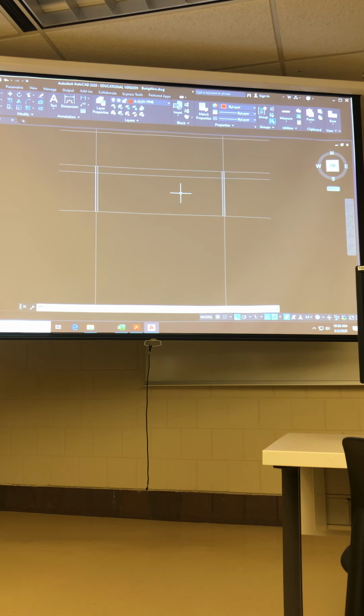So the next thing that I'm going to do here is start drawing my truss for the upper floor level. Again, I'm drawing structure first. So my next datum line up from my main floor top of sheathing was the bearing for the truss for the upper floor level, or my top plate for the exterior wall.